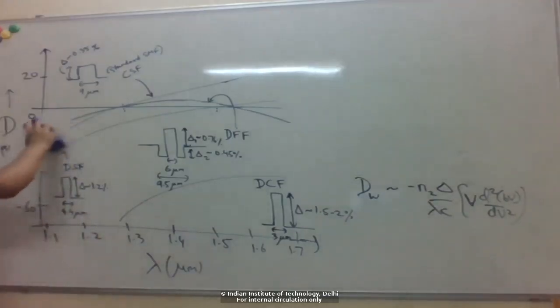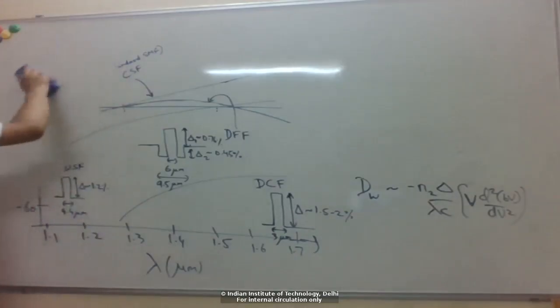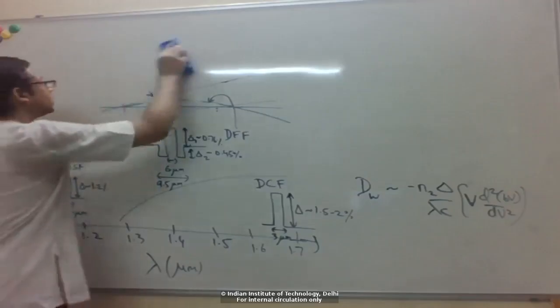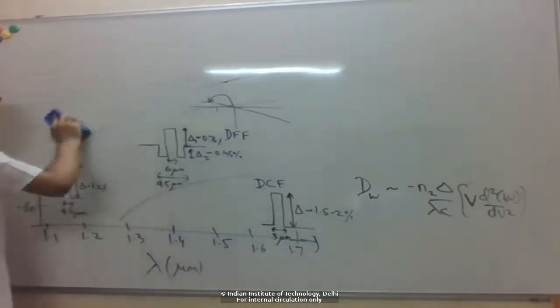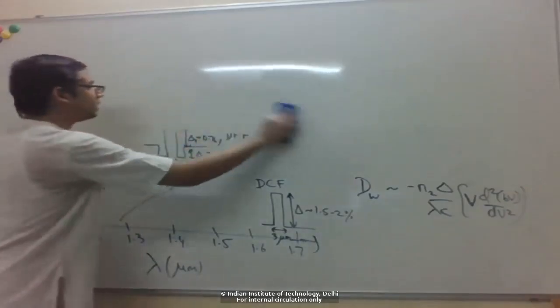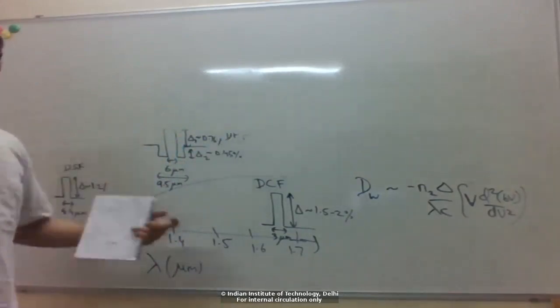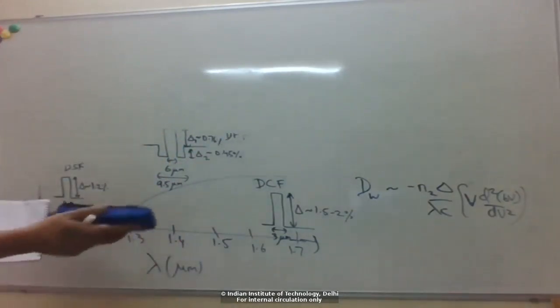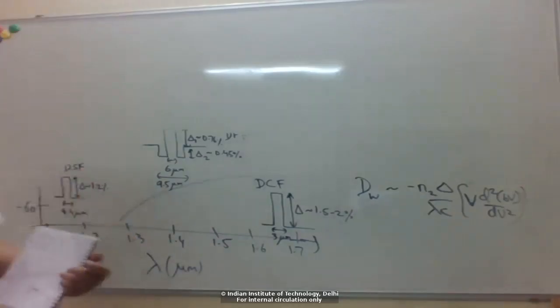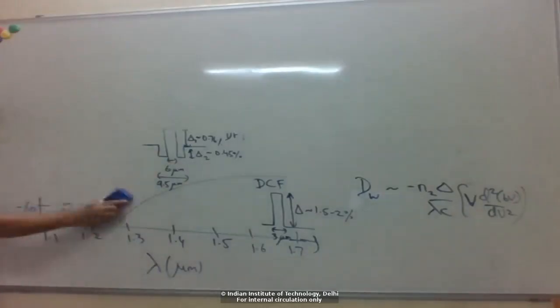So the next topic is another source of dispersion, which is slightly different. Okay, it's called polarization mode dispersion. So as the name suggests, it's a dispersion mechanism which is actually coming from polarization effects. So far, we haven't considered any polarization effect. Right? We sort of assume that the light is being guided in the fundamental LP mode, so it could be in some particular polarization, either X or Y. Okay. So some linear polarization which is sort of maintained along the fiber.